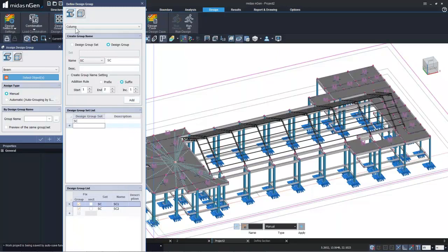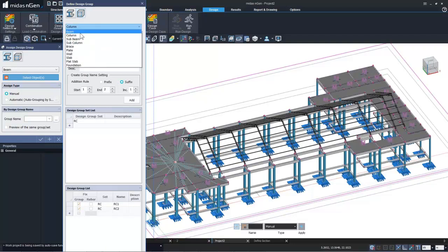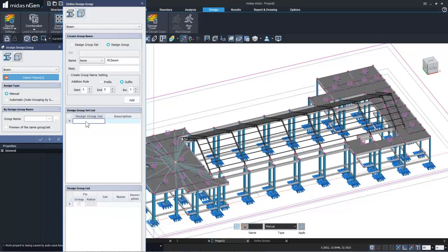Okay, then further, I'll go ahead to the RC now, and in case of RC, again, there is columns, so I'll just call them RC column over here, make a group name of RC, select that group, and add the type, RC1, RC2, like that. Then further, I'll provide over here for the beam. Selecting the beam from here, calling it beam, and selecting the beam set.